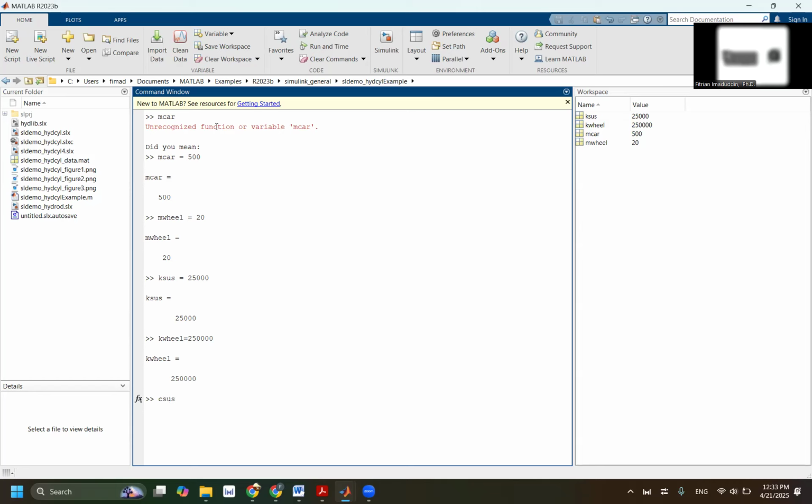C of the suspension, there's no easy way to say this, but you can actually predict it if you want to. Normally every suspension is designed to tend to be more underdamped. It's normally set in the value of 0.2 to 0.5 zeta for a comfort mode. For a sports car, it's normally between 0.7 to 0.8 or 0.9. Because in a sports car, you like it to be stiff. You don't like to drive a sports car and be bouncing like this. You want it to be really stiff.